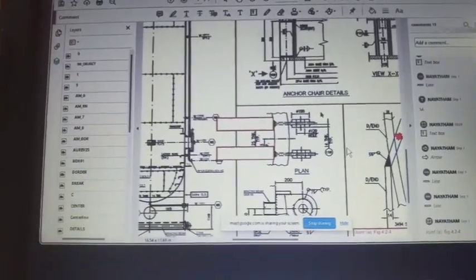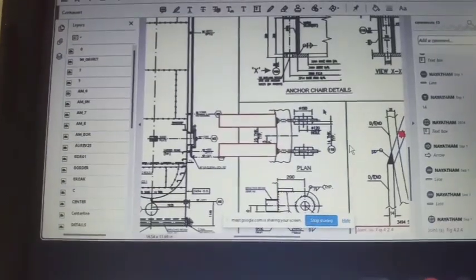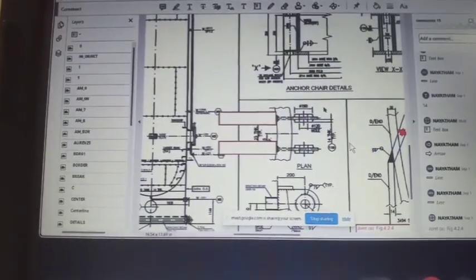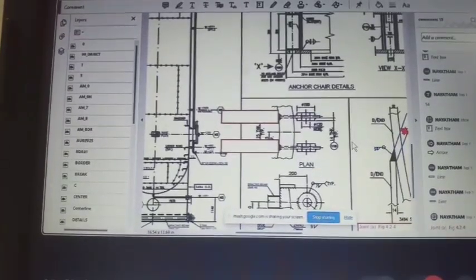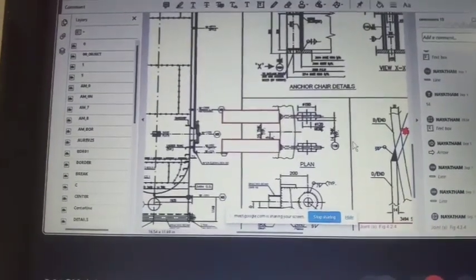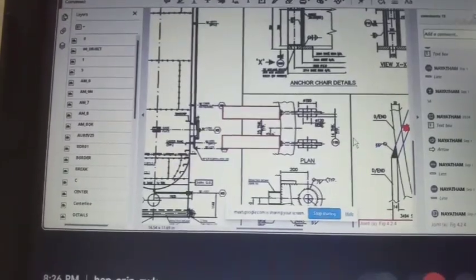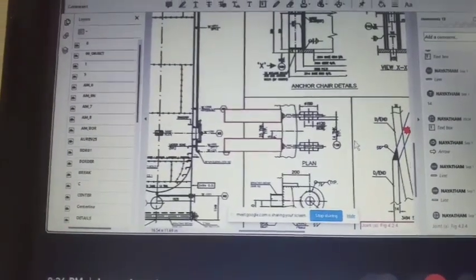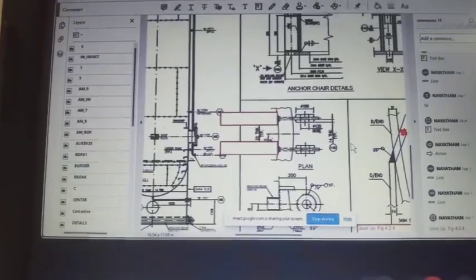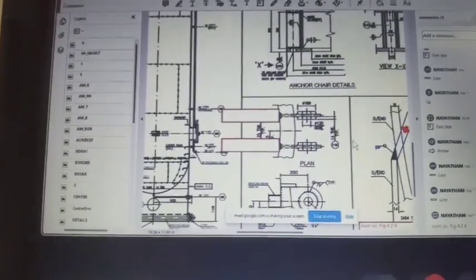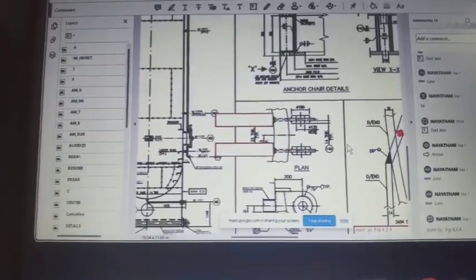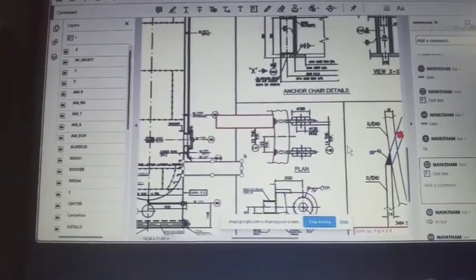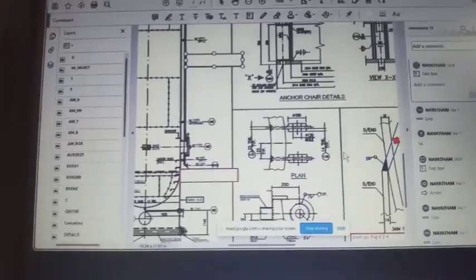And what is the material? It is IS 2062. This is equivalent to SA 36. Okay. So there must be a problem with the ovality, no? Is that the reason you are asking for the struts? Yeah, ovality. They have already shown a bracing beam, ISMB 150. Yeah, 150 they have shown, but I need to verify.